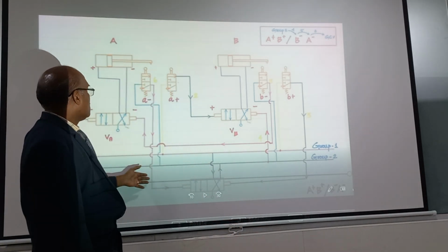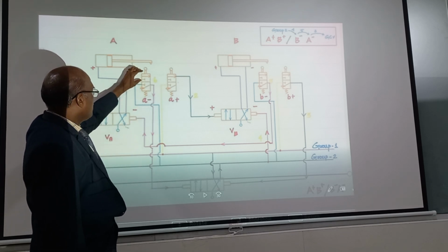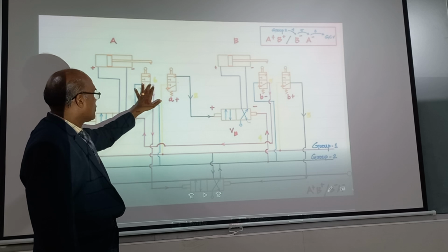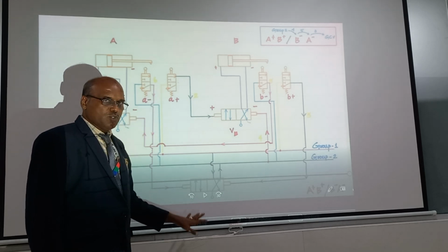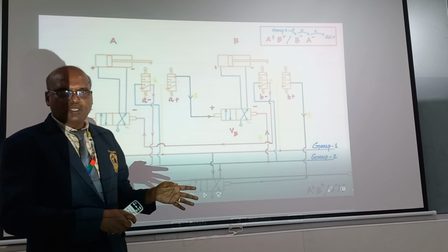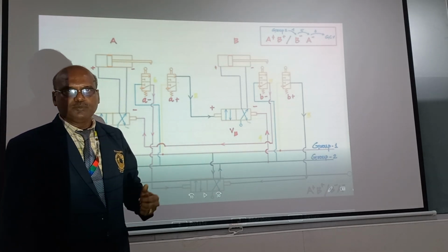Now once A minus occurs, the group is over. Group over means from A minus, this will go to the cascade valve. So now the operation is over. Okay, this was the simplified form of the double electric cylinder in the cascade method. I hope you understand the video very well.